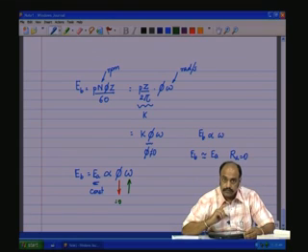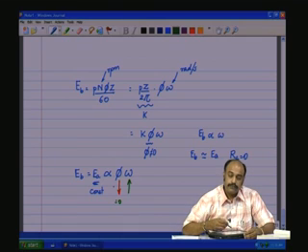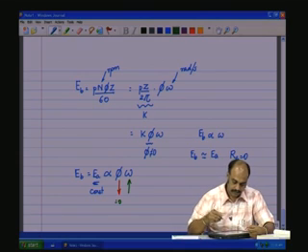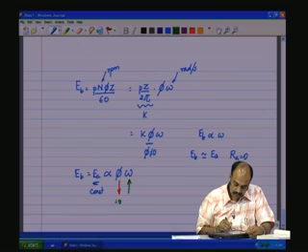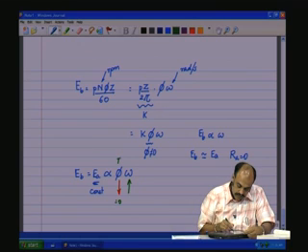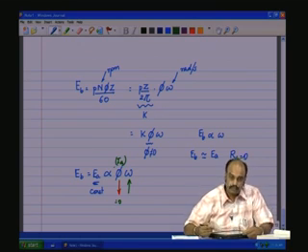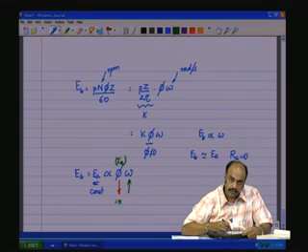But in the case of the series motor, when the field coil is broken, Ia is also 0, because the flux is proportional to Ia, and omega is also a function of Ia.